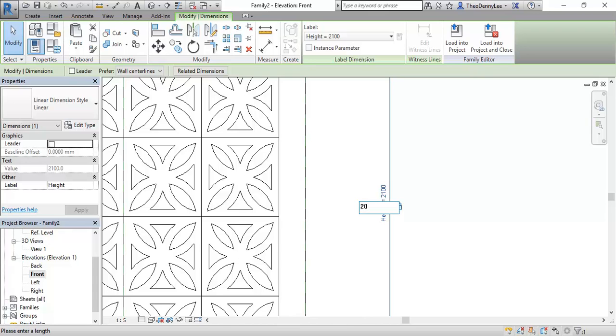Oh, yeah, you've got to have the group and associate option turned on. When you click on array, it'll give you that option to group and associate. So that has to be on. Yeah, and then you might not see it, but it'll be there. If you just type, it'll go in. Yep. Oh, I'll come and have a look and see.